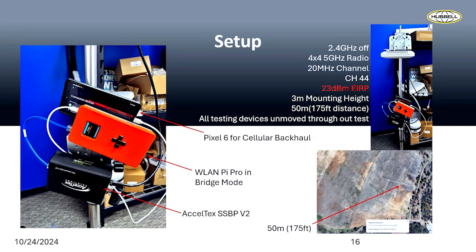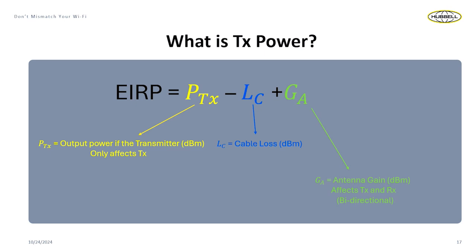The last thing I'll point out is that we're going to test all these at the same 23 dBm EIRP. And I point that out as it's the ERP and the forced spatial streams earlier because I did slightly mislead y'all. The equation that I gave earlier is not the full equation for ERP. There is a final portion for that. That's the MIMO gain that we're not considering. So in this case, we're using the four spatial stream APs, so we have to do the MIMO calculation, which in this case is about 6 dBi of additional gain that we have to account for. So when you see later on the stats of what the transmit powers are set to and what the antennas are, they'll only add up to 17, but that's because we have to account for the MIMO gain as well.